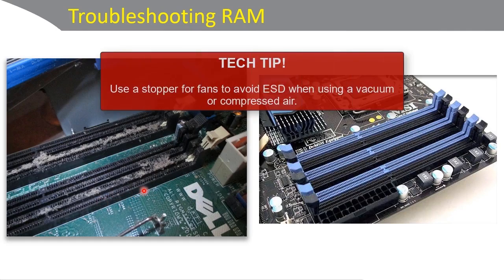And also any fans that might be there, you want to make sure you put some type of stopper in the fan so that it doesn't move. If you're using a blower and the fan starts to move, that could actually generate electricity. It could cause a charge. It could cause a discharge, some ESD, so be careful with that.